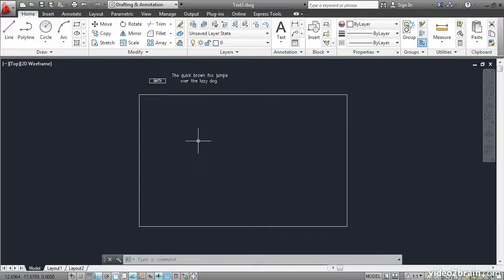In this lesson, you will create multiple paragraphs of wrapping text by importing some filler text into the mtext command. You will then proceed to edit the block of text so it flows into 2 columns, and then you will adjust it so that it fits within a rectangle.